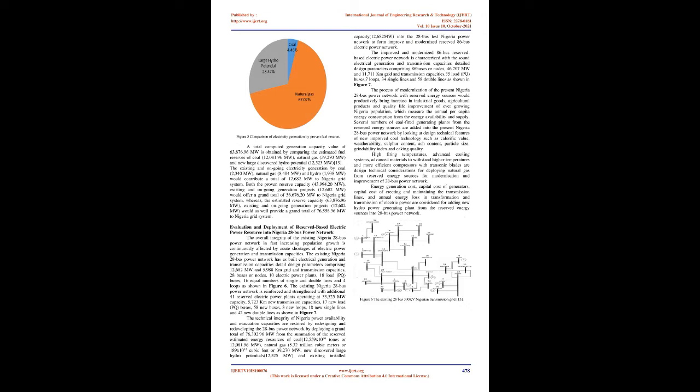The continuation power flow network is formulated, and then implemented using MATLAB Simulink Power System Analysis, PSAT, program. The purpose of the continuation power flow is to find a continuum of power flow solution for any change in load. The general principle behind the continuation power flow is simple. It employs a predictor, corrector scheme to find a solution path of a set of power flow equations that have been reformulated to include a load parameter.